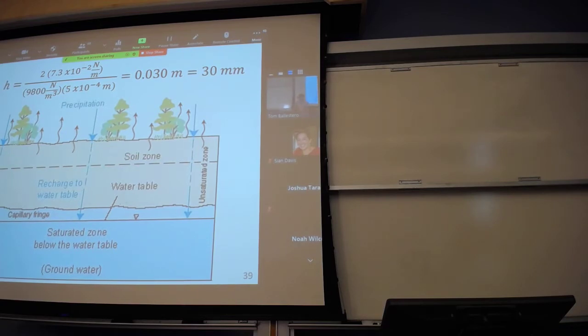What's driving it? Surface tension. What's happening in these little pore spaces, assume that the capillary fringe is not there. You just start with this system. The water starts wetting the sand grains. That starts deflecting the surface from other than a plane surface. And now the fluid just rises up, just like you saw it happen in the lab experiment.